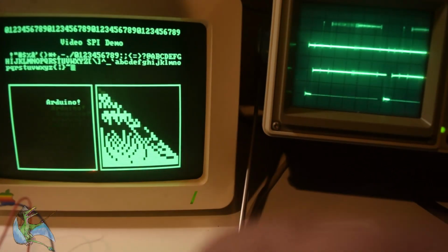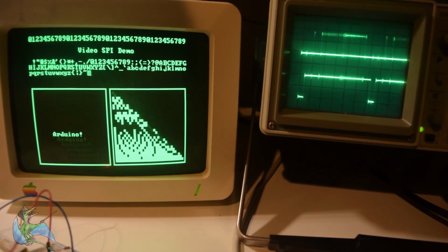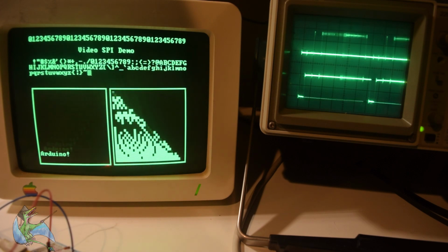Now that would be nice, in that there'd be no obvious black lines like this, but each line would only be refreshed at half the speed, which doesn't really matter if you're watching TV. But if you're displaying graphical dots, it will flicker, because 30 hertz is a little below most people's persistence of vision. So that's why non-interlaced is usually used for NTSC displays.